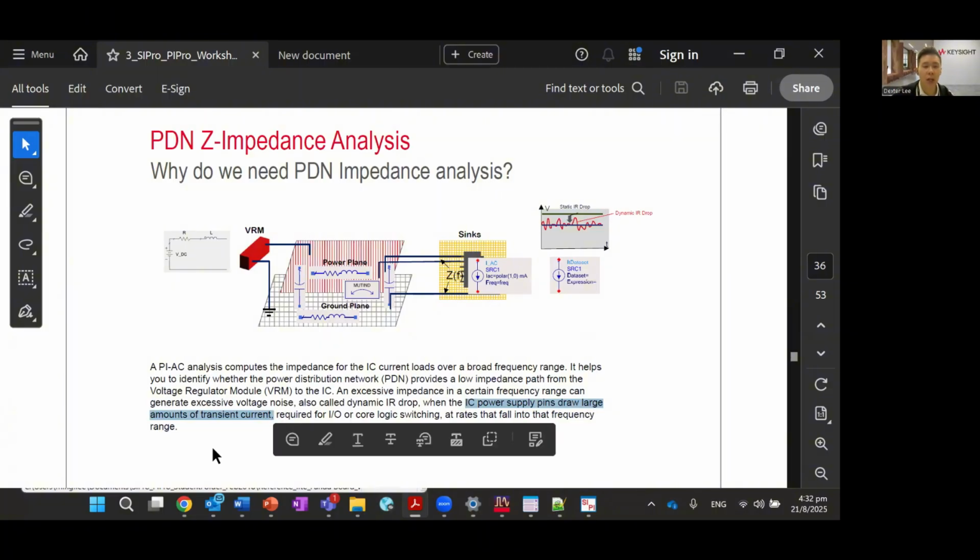I think it's also good to run AC to ensure there is not much resonance. We have another simulator called power plane resonance. It finds resonance coming from your power rail, because all these resonances may potentially create EMI issues. So PDN impedance is another important analysis to work with, and a lot of times PI engineers will have a target impedance to work with.